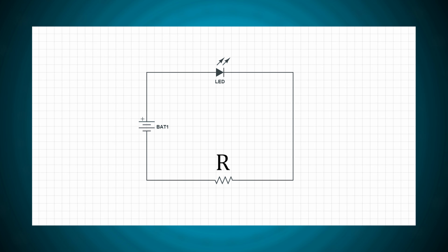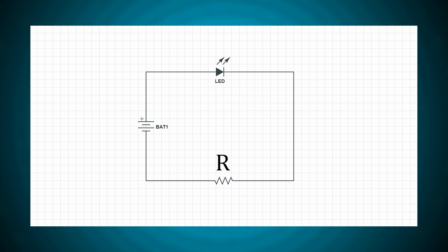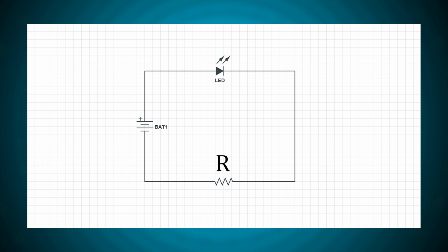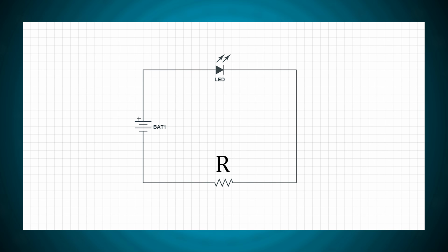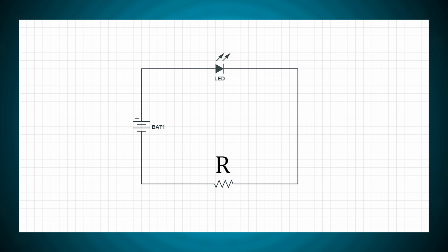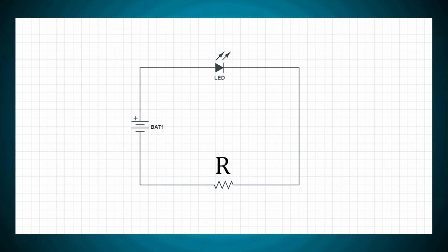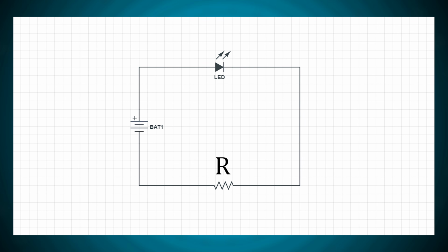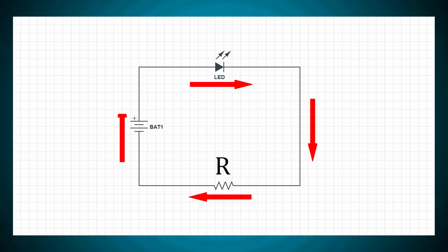Here's the general circuit we want to use to power an LED. This is a typical serial connection, since all components are connected in series, and R is resistance. Current flows from positive to negative, passing through the resistor. As we, again, remember from physics class, current strength in a serial connection is the same over the entire circuit, since there is only a single pathway for the charge to flow.